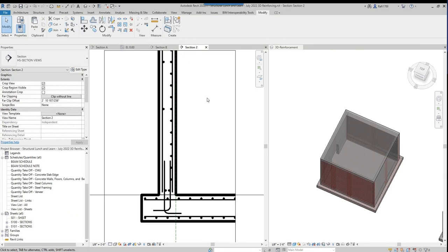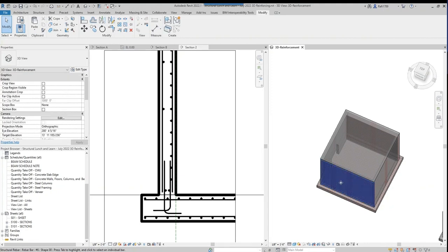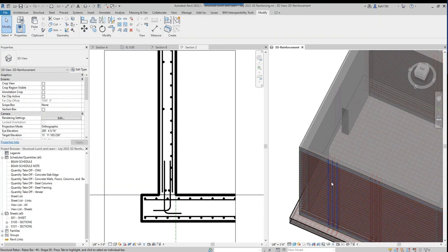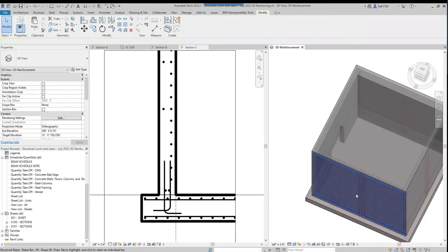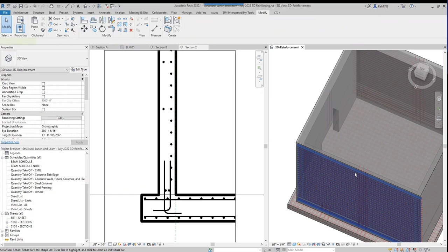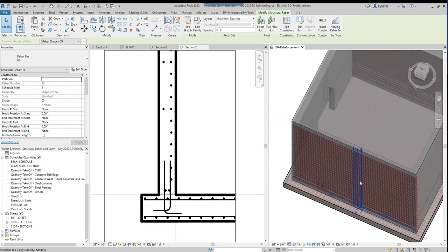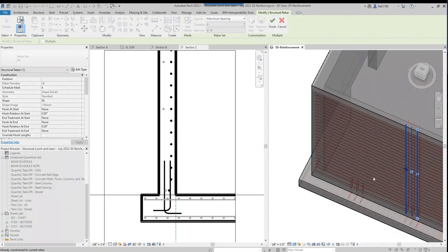But if you don't do it with maximum spacing, then you're having to model all these bars, and that's when it starts becoming a mess. But you're like, I don't want to see this rebar here. I want to see that rebar here. We're interacting with the same mat. I'm able to select what I want to see differently. But with the vertical bars, if I had 3 sections across this wall, I could do maximum spacing, and then I can edit the constraints.